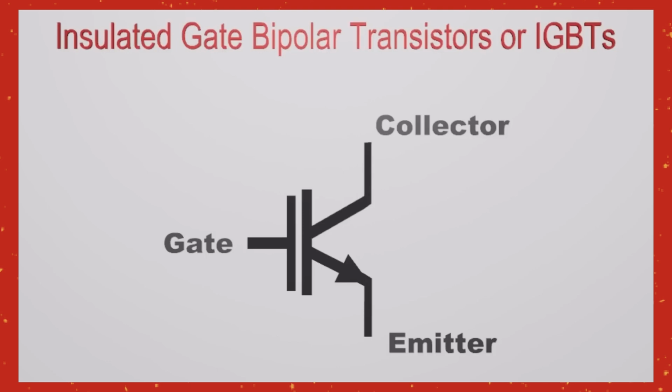By opening A and B and closing C and D at the same time, current starts to flow through the bulb from right to left. Likewise, turning the IGBT switch pairs on and off reverses the current direction. That means alternating current is generated.